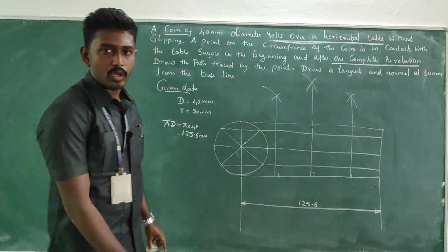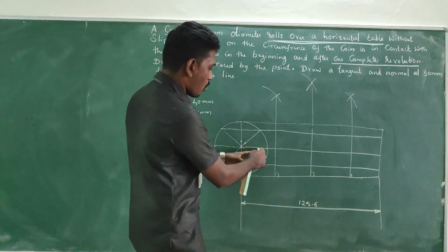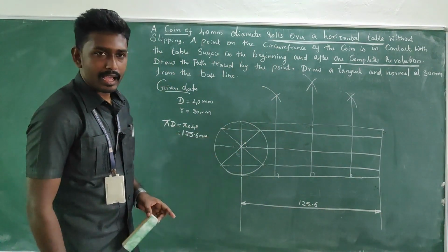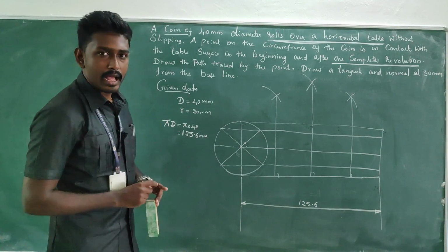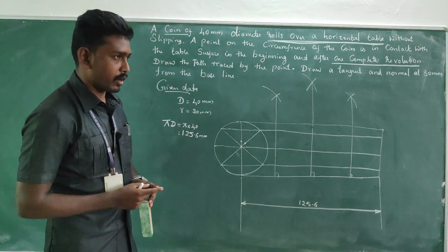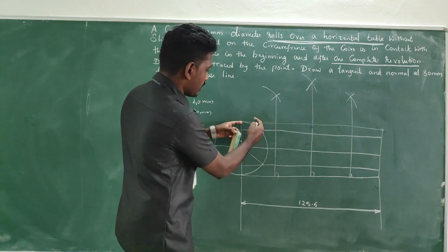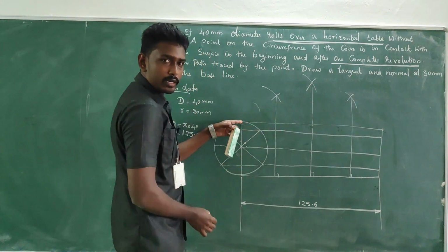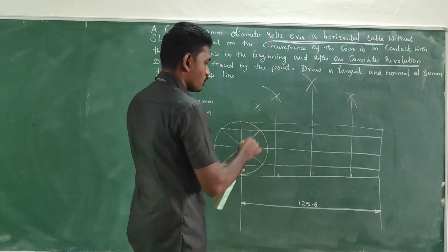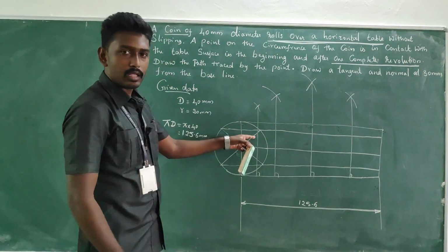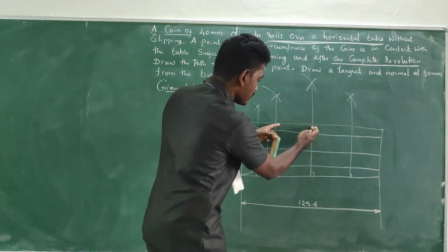You can divide it into equal parts. So now we have 1, 2, 3, 4 equal parts. Again, our aim is to divide it into 8 equal parts. So this is our segment. Take more than half and go for an arc. Keep at the end, go for an arc. Drop a line. You will get two equal parts.